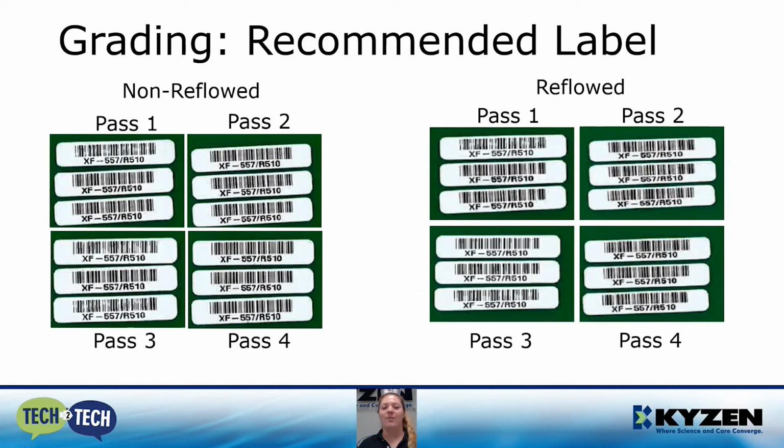Let's look at a recommended label. So this has gone through the same process as the labels in the previous slide, and what you're seeing in our non-reflow condition, the labels are adhered well, you're not seeing any peeling or flaking at the edges. The ink is legible through each of the wash processes. You haven't seen any dulling, any changes. Once we go to the reflow condition, you're seeing the same. Overall, this would be a complete pass in both reflowed and non-reflowed conditions.